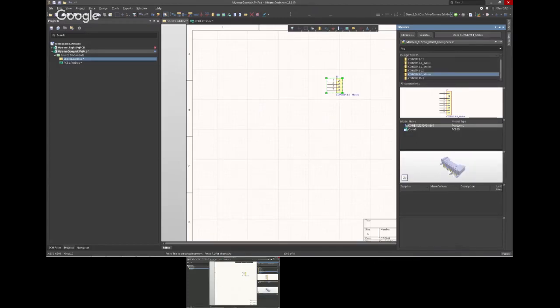So we can embed step files today to have that nice representation, because Altium Designer is a 3D aware platform. So you can embed a step file and it gives you that nice representation of the board, and you can run your component clearance checking. But with a connector, you not just get this step, you actually get native solid part. So I can embed solid part and I can embed parasolid. In addition to step file, you can keep your generic models if you have.